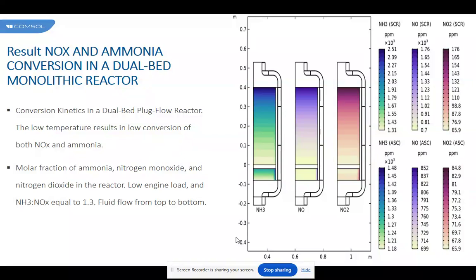Further related to the channel size is the average washcoat thickness as well as the external surface area of the washcoat that is exposed to the gas. These factors can both affect the conversion obtained. The use of an inlet diffuser combined with external heat losses from the converter gives rise to non-uniform radial velocity and temperature profiles in the monolith.